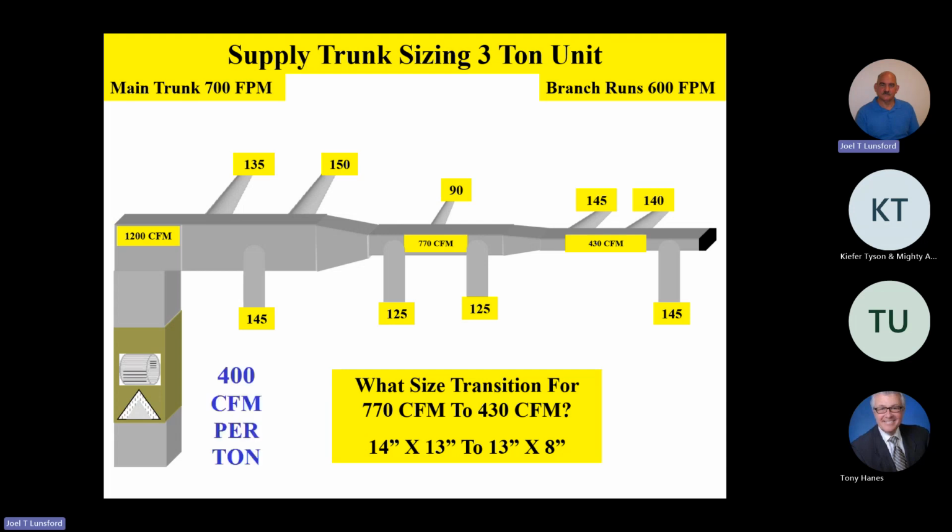So as we build our duct systems out, we want to be very, very aware that if we design our duct systems with velocity in mind as our main criteria, we'll always have a nice quiet system. It'll perform properly, and if we put dampers on each takeoff, we'll be able to balance that airflow perfectly. And fellas, right now, this duct system that we've just built together, if you built a duct system similar to this in design, I promise you that system would allow you to properly charge your unit, and it would also give you a wonderful humidity control and quiet operation.